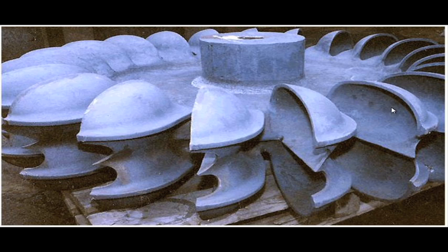Usually, the speed of the bucket is specified at the central plane, that means the central line of the bucket. That means the bucket has a width in this direction at the central line. We calculate the linear speed by multiplying the angular velocity with the radius at the central plane. Now, one thing should be clear: inlet and outlet do not vary in their velocity, that is the rotational velocity of the blade, and they are at the same radial locations.